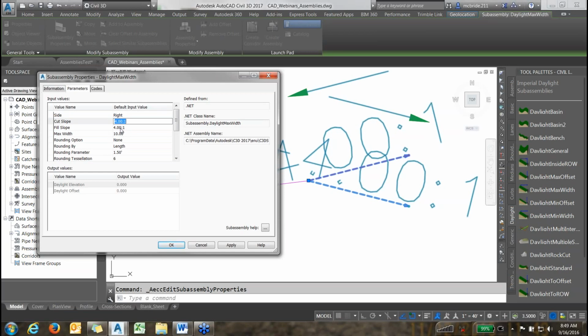And in the case of a waterway, you don't want that to be too steep, right? So if 6:1 is usually our minimum, then that's what we'll put in there. So in this case, I'll put 6:1. Now you can do 8:1, you can do 10:1. Whatever you used in the past is still okay, and you can change this later if it doesn't fit too. And I'll show that here in a second. Okay, but right now I want to change my cut slope to 6:1, and my fill slope I want to change to 200:1.